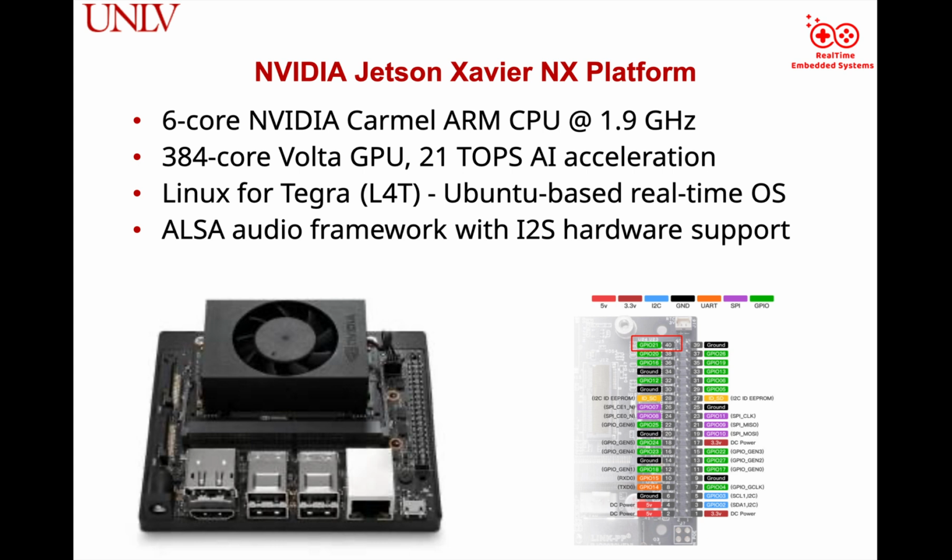So I chose the NVIDIA Jetson Xavier NX platform. Why? Because I have been developing my project with this NVIDIA Jetson, which is so small, and it has a 6-core ARM CPU, a 384-core Volta GPU, and 21 TOPS of AI performance.